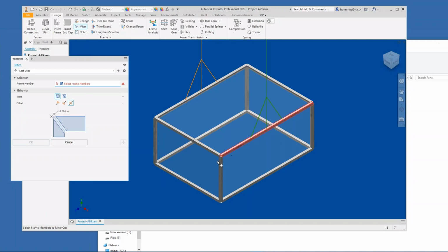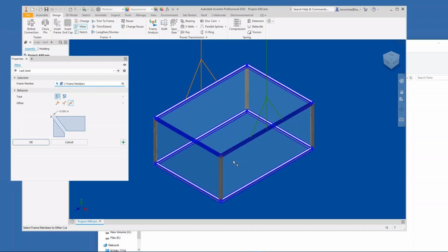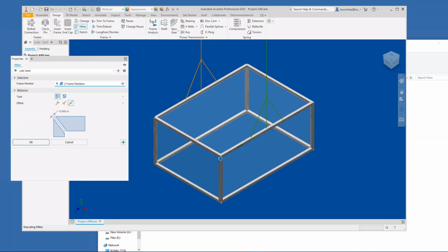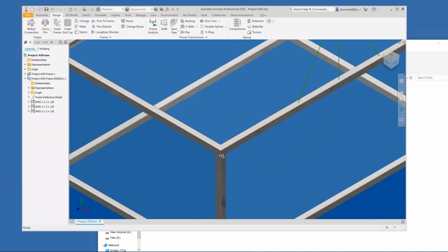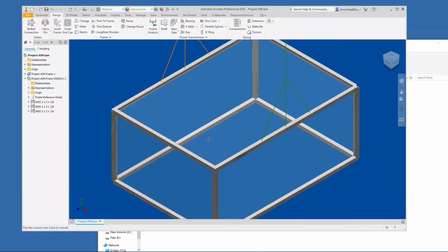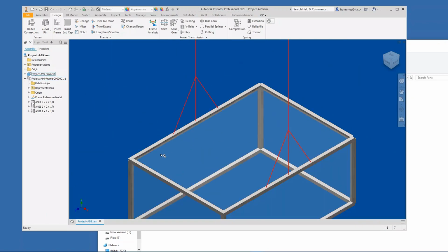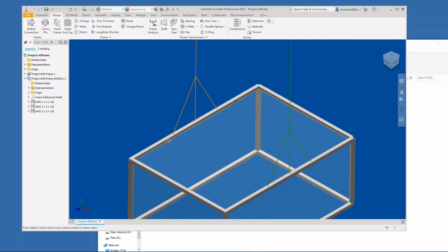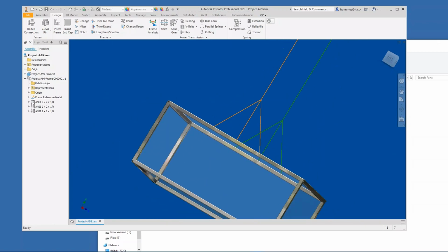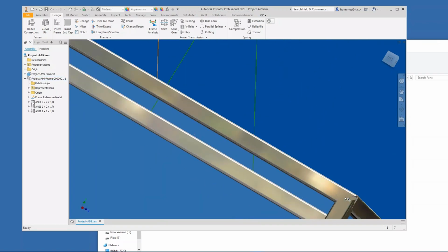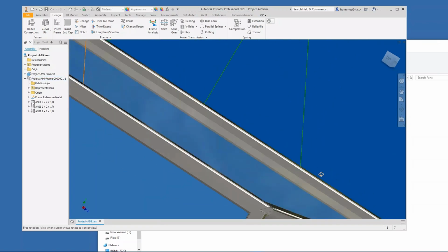Right, so what you want to do is miter the corners here. I'm going to miter those. You can see when I select, it selects all of them. So what's happening here is it mitered here, right? But since this end is a copy, you may have to change the orientation around a little bit. Right, you can see this is off 90 degrees.